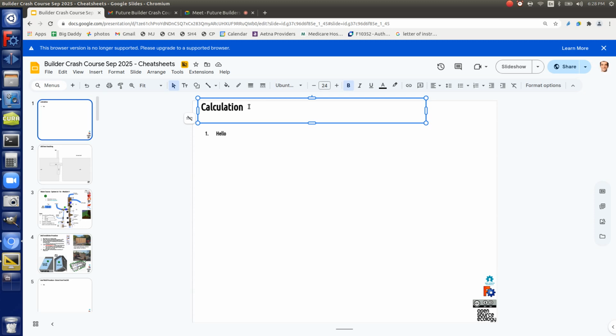We've got, say, 300 for practical purposes for wood, assuming there's knots and things. Let's do that lower level so you're safe. Steel, you got tens of thousands. Concrete, you got several thousand. So for wood, the question would be, how much can a 4x4 hold vertically? Assume it's 4x4 inches, like 16 square inches.